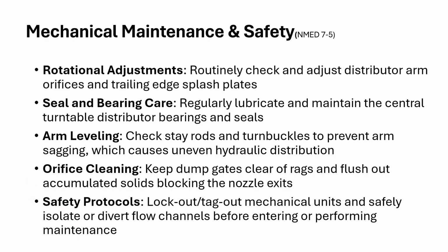And whenever you're working on these systems, second time in the course, I'm going to mention safety protocols, particularly lockout tagouts for mechanical units. Whenever you're working on these, you want to do a lockout tagout. You want to divert any influent. You want to isolate the system while folks are working on it and doing maintenance on it. Okay, another safety issue.